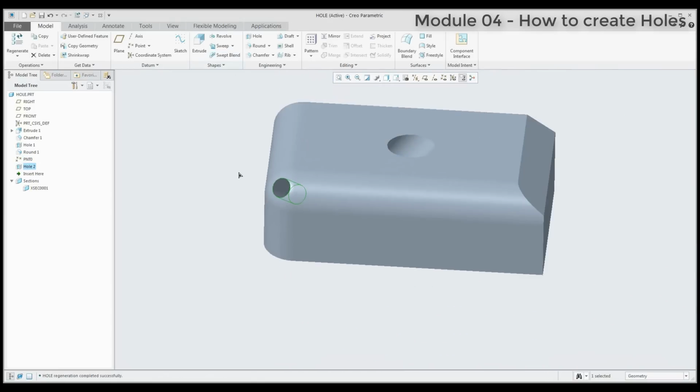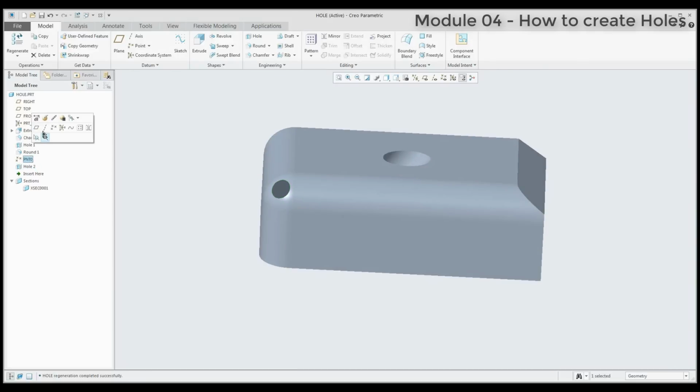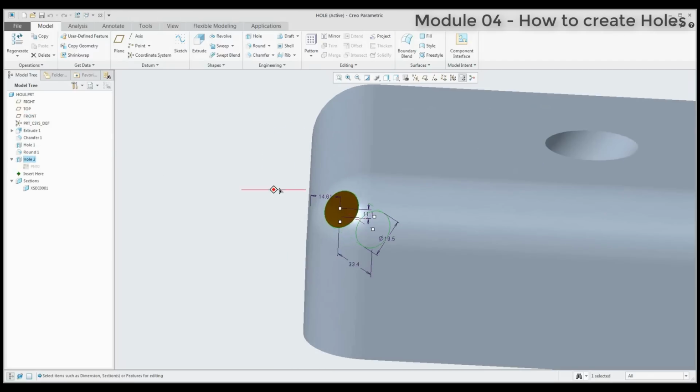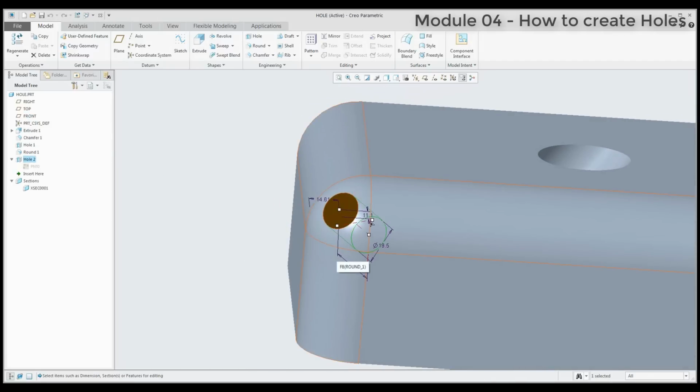If you will move with the point, the system will move with the hole. So you have a references, and the question is, if you don't want to see this point, because this point is necessary for the hole, you can set and drag to the hole. So the system will automatically make a group here, and the point is hidden. So if you would like to edit right now, the placement for the hole is specified by this placement of the hole.